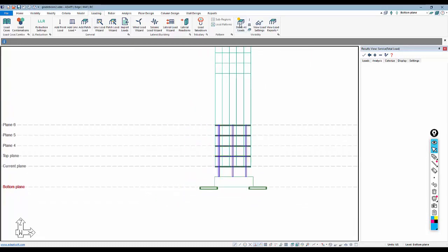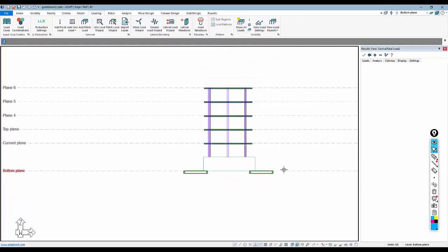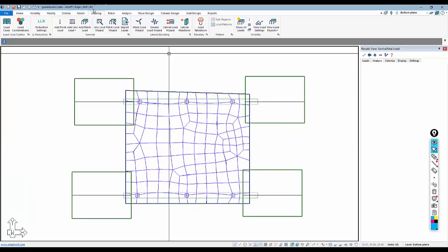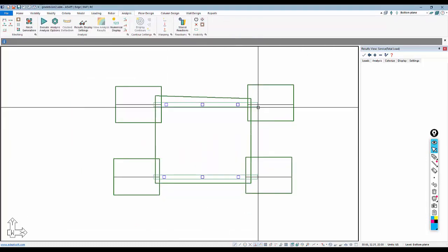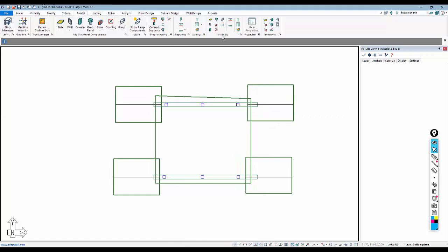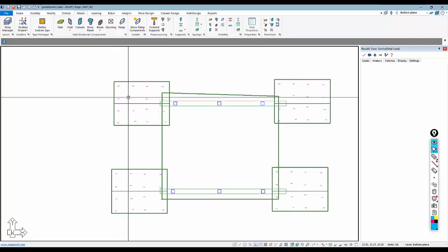So what we're going to do now, let me turn those loads back off, is we're going to analyze this globally. We first need to mesh this. So let's clear out the mesh for the full structure. And we want to show one more thing. If we go to Model Visibility Panel and we turn on the point springs, in this case, what we've represented in terms of piles are springs. These are just point springs.